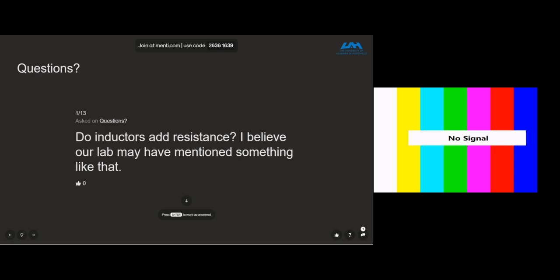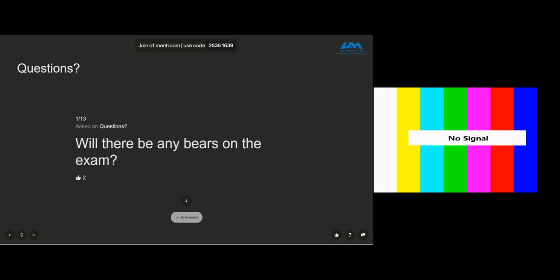They are related, and inductors are going to have resistance even if they're made of conductors, right? We said that resistance is equal to rho L over A, the resistivity times L over A. You really have to use a long length of a conductor to get any sort of inductor. So there is going to be some related resistance, but it's not usually as strong as an actual resistor.